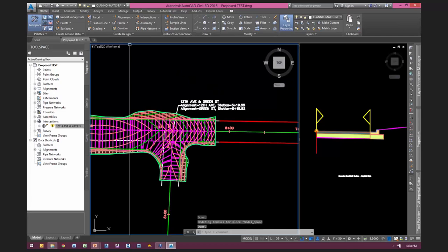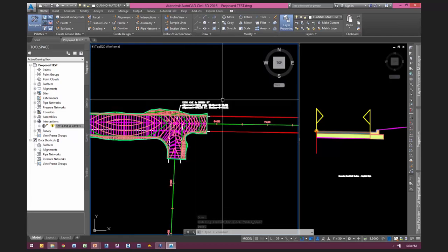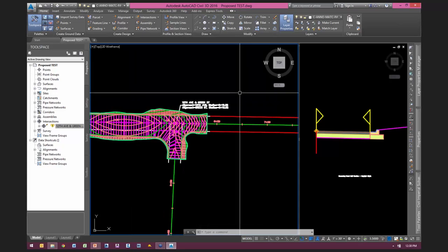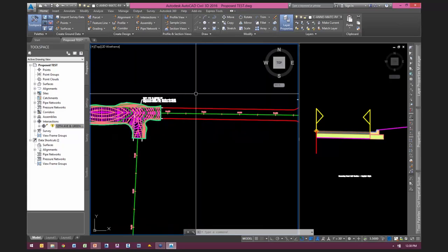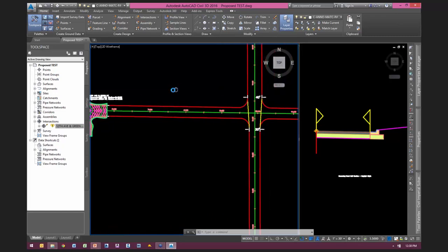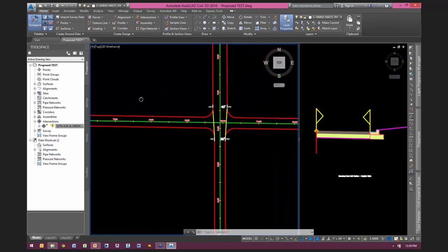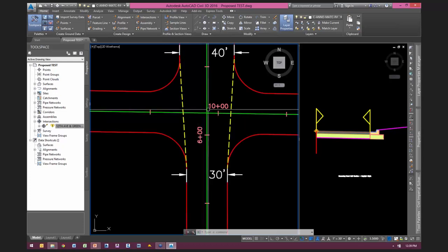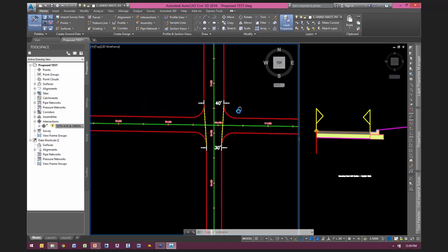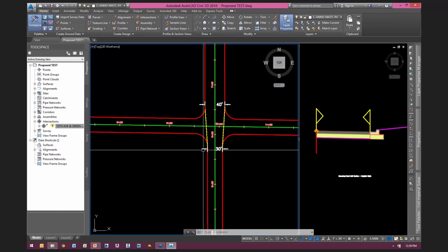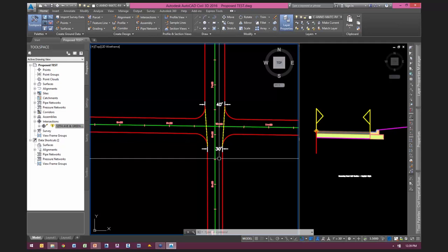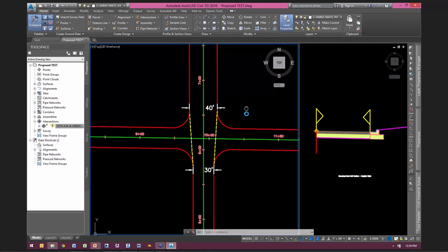All right, let's continue on here. If I get time, I am going to show the custom assembly set thing, but I do want to make sure to get through this other intersection. So given the time, I'm going to move on, and we'll touch on the assembly set at the end if necessary. All right, a different intersection. How do we handle this? If you remember, we went through the intersection wizard, and we could only specify one width. We can't do one for each side of the road, but only one width in total.